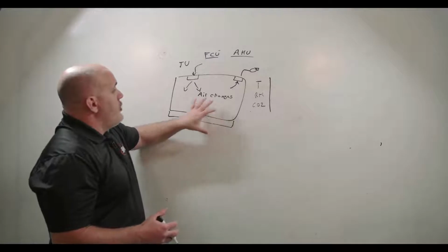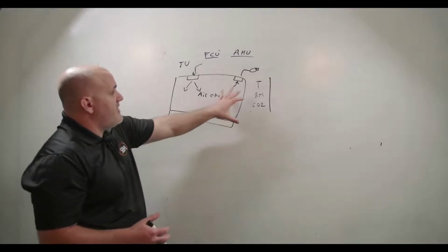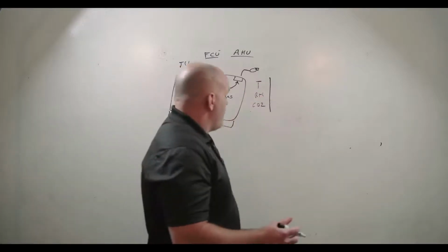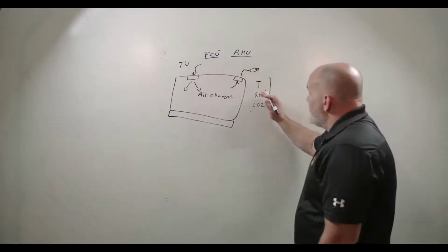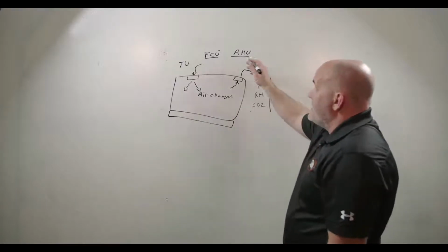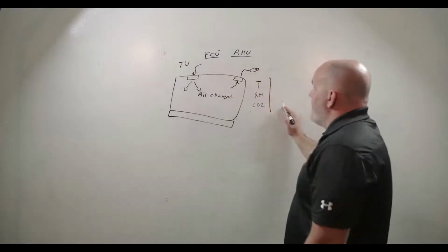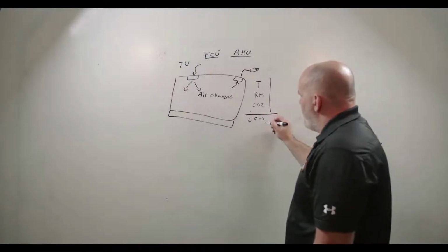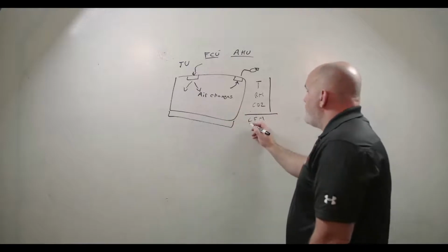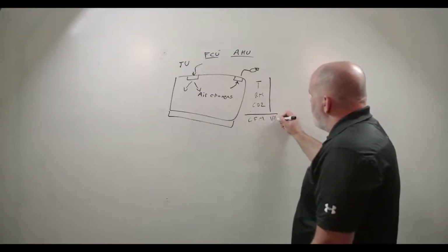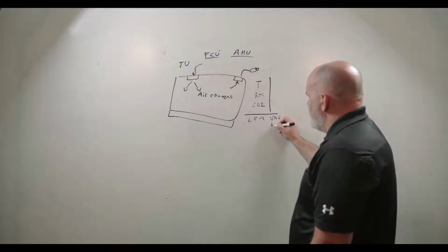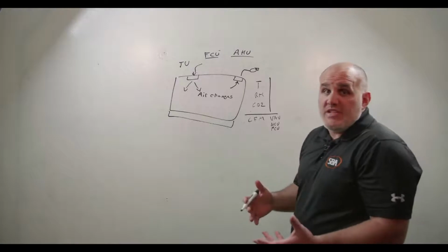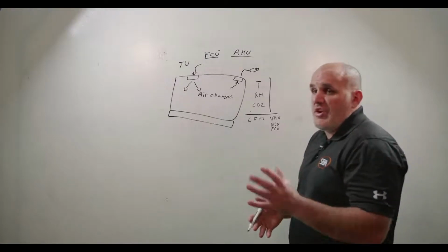That being said, we're primarily focused on making sure we get our air into the space and get it out of the space so that we can then impact these variables over here on the right. So temperature, and these variables directly correlate with these units up here. So the CFM, which is kind of the overall variable that we are controlling, our airflow, that directly correlates with either the VAV box or the AHU/FCU. And for a VAV box, we're going to stroke dampers inside the VAV box and regulate the airflow.